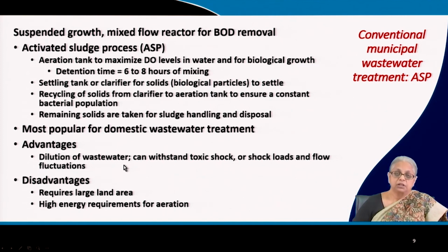Some of the major advantages. Why is it the most popular? The first thing is it allows dilution of the wastewater, and that is very important because this dilution provides a shock absorbing capacity which other processes do not have. So it can withstand toxic shock. So supposing someone in the city dumps a load of toxic material, that will not kill the biological process despite the toxicity of the material. So that's because of the dilution.